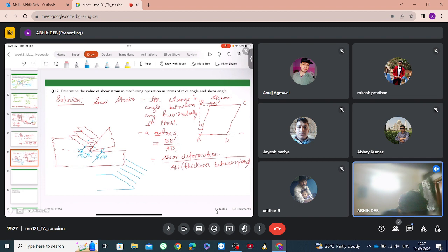Because of the action of the tool, what happens is this point, it was like this, a plane like this. So this point now gets shifted here because of the shear force by the tool in this direction. The point gets shifted here. There is a shear deformation. So this point which was supposed to be here gets shifted here. That is why there is a shear.